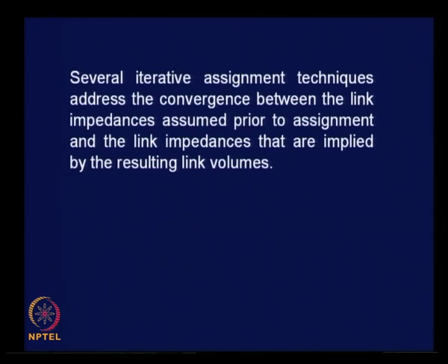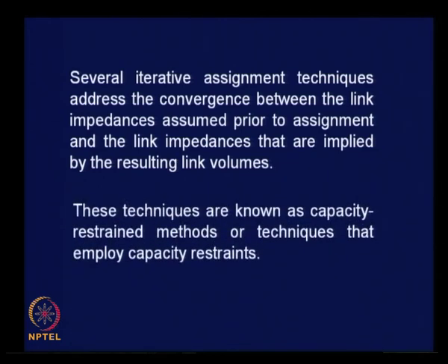And for this purpose, several iterative assignment techniques address this particular convergence between link impedances assumed prior to assignment and the link impedances that are implied by the resulting link volumes. These techniques are known as capacity restraint methods.